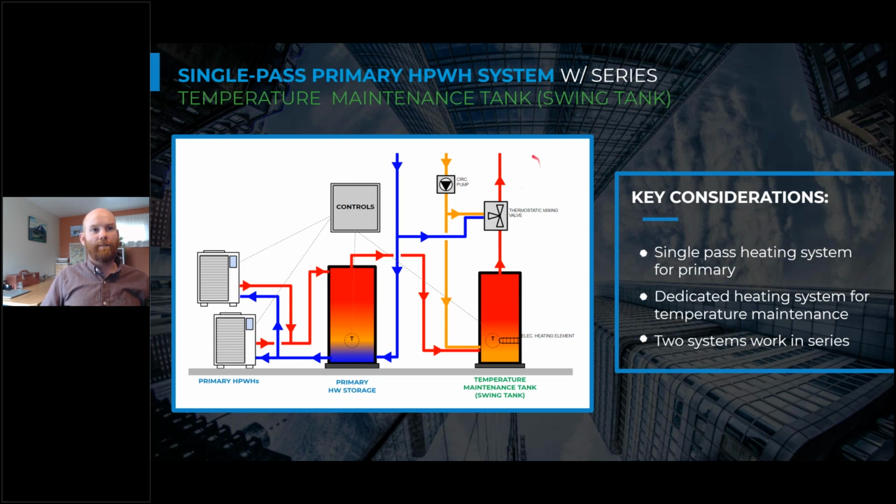So the amount of water people use and the periodic use of that can be a very effective way to offset these circulation losses if we overheat that water and pipe it as I'm showing here. And this design is really, really appropriate for CO2 or R744 heat pump water heaters, because those heat pump water heaters can only be configured in a single pass heating cycle.